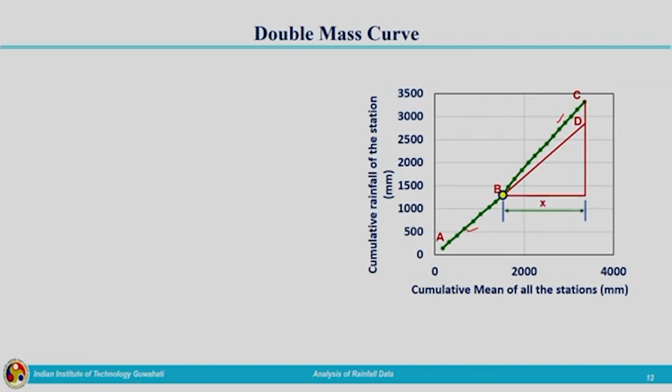For that we are taking the ordinates and abscissa. So, slope of BC can be obtained by taking the ratio A divided by X. Now, coming to slope of BD, we need to have the ordinate that can be represented by B. Slope of AB and slope of BD are the same, it is the same line only, BD is the extension of AB. It can be calculated by taking the ratio B by X.